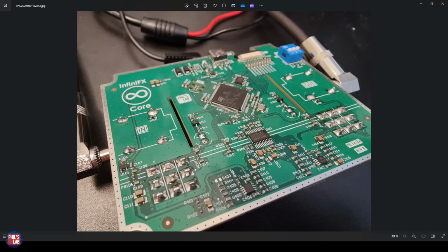So what we do now is we attach back this quarter inch input jack and we connect that, as we saw at the beginning of the video, to the QA403 and pass in a sine wave of a known frequency and a known magnitude, and let the QA40 software calculate the signal to noise ratio for us.